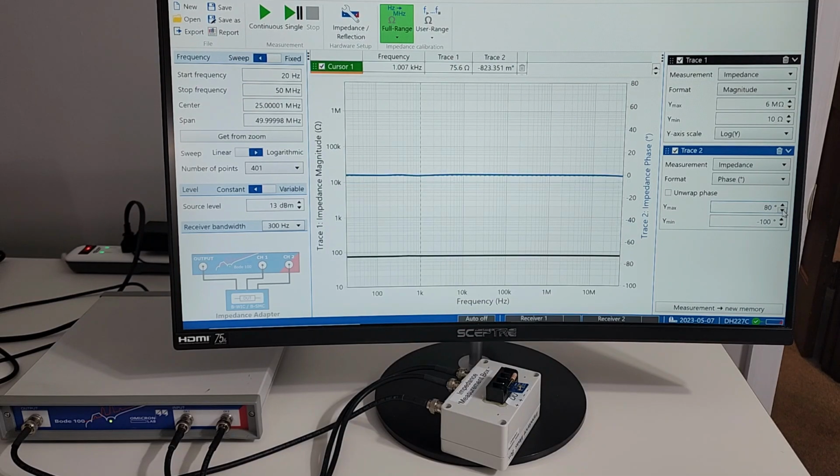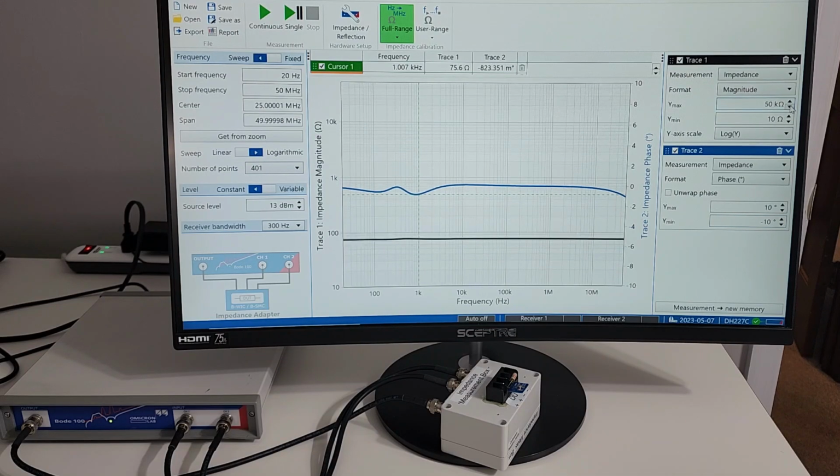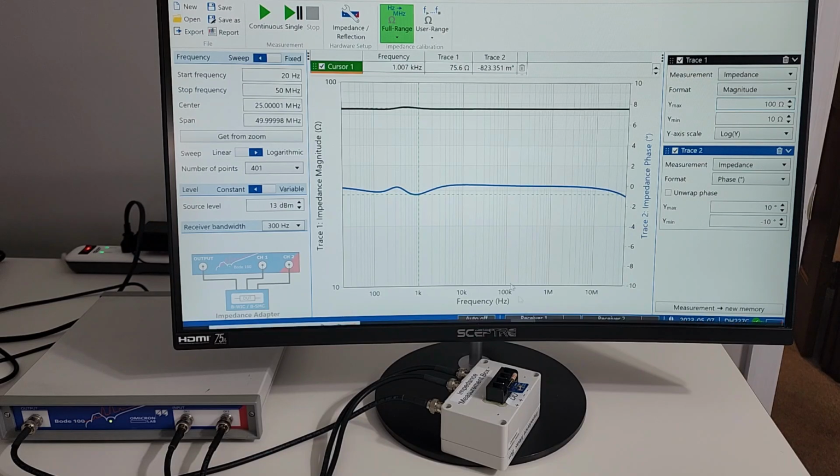Let's change the scale here. Instead of going from 100 degrees to minus 100 degrees, let's go 10 degrees to minus 10 degrees, and let's go 10 ohms to 100 ohms. So we can see this on a greatly expanded scale. If I find where my phase is off by the largest amount here, we're off by about 0.85 degrees, which isn't bad considering I really didn't do much of anything to try and match these RC and L over R time constants that accurately. And as you can see, I'm at about 75 ohms. We got our 74 ohms of our inductor, and we've got a maximum value off at a little more than 76 ohms, which isn't bad.